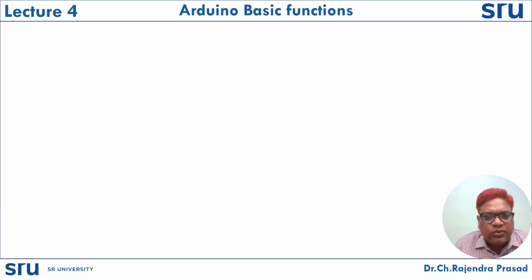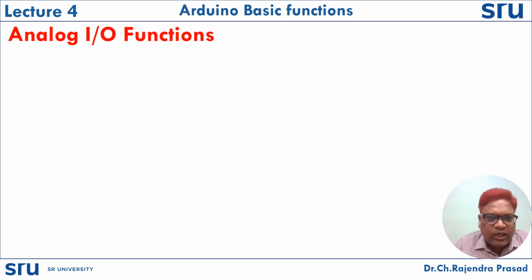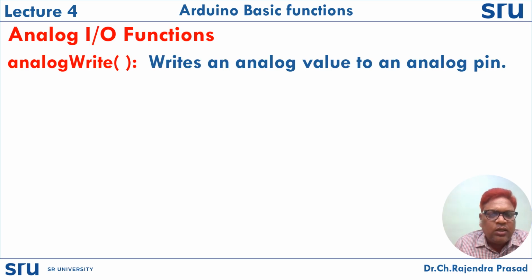Then we need to discuss analogWrite. Another analog I/O function is analogWrite. This function writes an analog value to an analog output pin.